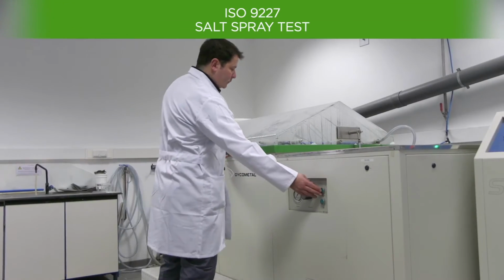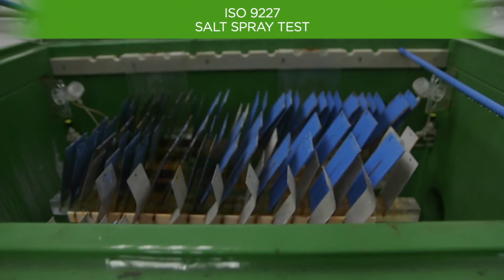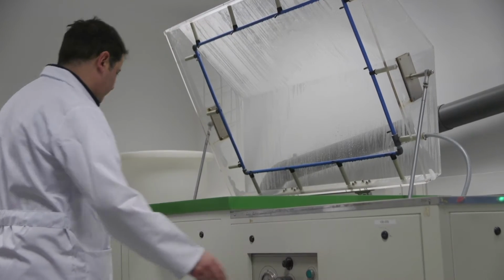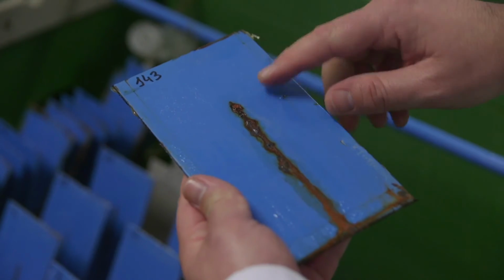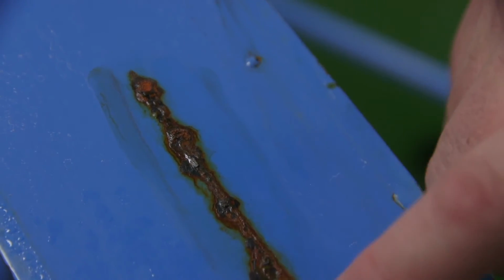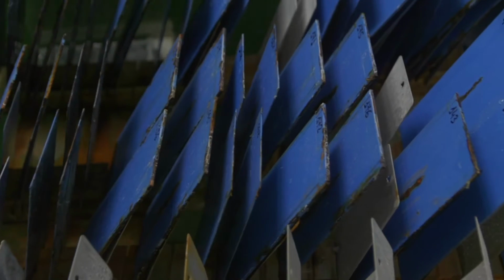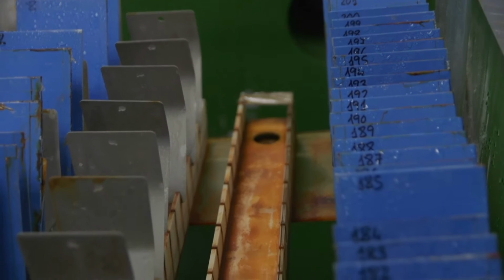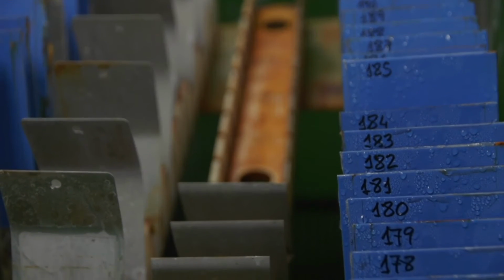Salt spray, ISO 9227. In this test, the paint test cards are subjected to continuous projection of a 5% sodium chloride solution with a pH between 6.5 and 7.2. The paint test cards are incised to cause the onset of corrosion. These paint test cards are assessed every few hours according to ISO 4628.